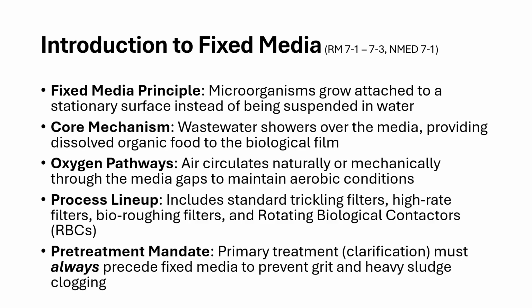In fixed media reactors, we have a biological film or a slime, if you will, that covers the filter media. We'll find that the rock and the other media that we have in trickling filters, the biological mass is attached to those, and we pour wastewater over that media and allow that wastewater and the organics to come into contact with this film or slime, and it's on a fixed media.